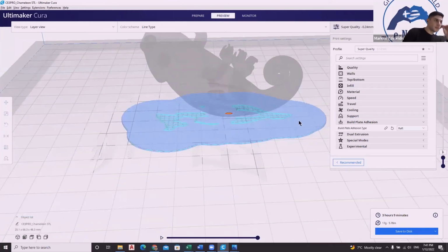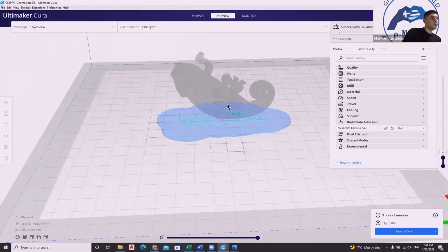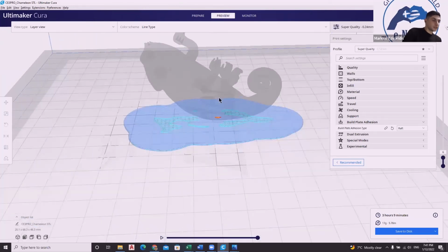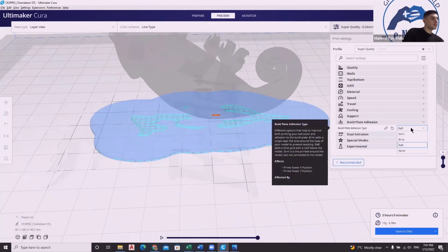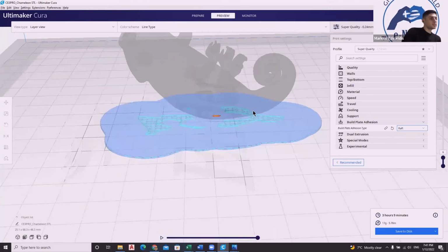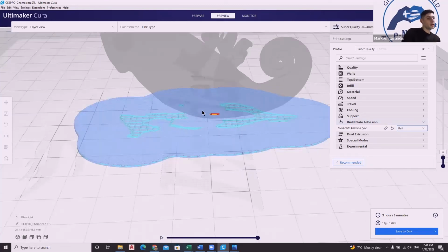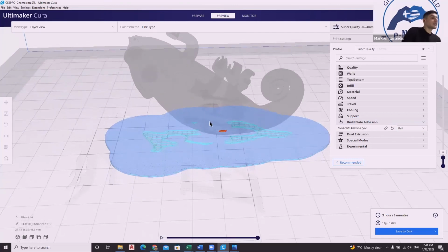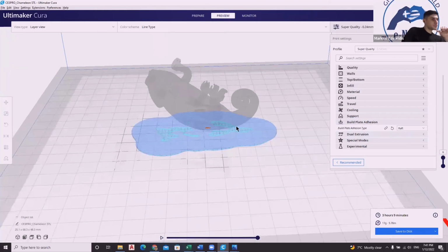Maybe you will use a little bit more material, but it's the safest way to go when printing for the first time. Maybe your bed is not going to be leveled right. Maybe you will need to do some tweaks afterwards, but trust me, for your first 3 to 5 prints, use the raft build plate adhesion because it's the safest one. It's the one that will help you print easy, and your print will not fall down, will not get unstuck from the bed. Generally, it's a better way to print.